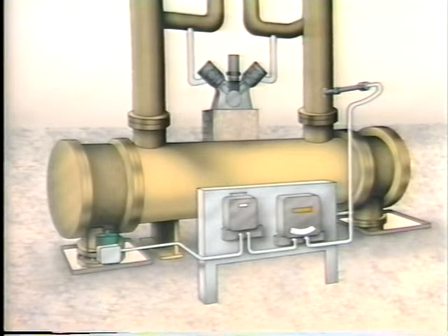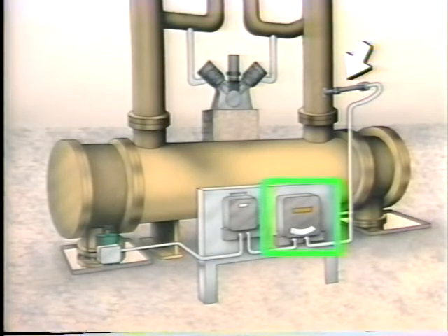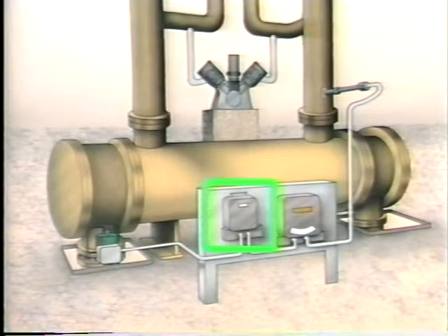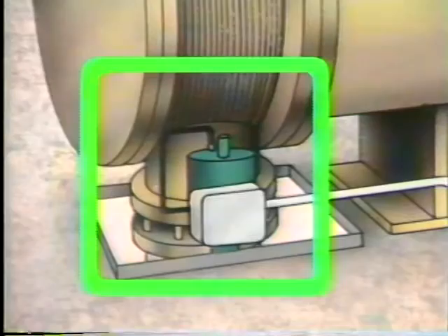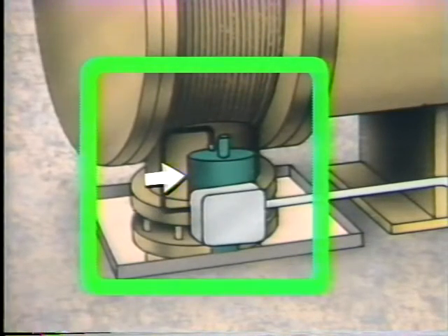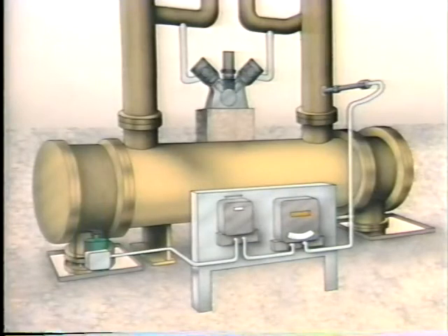The primary element in this system is a temperature sensing bulb and capillary tube that are connected to a sensing mechanism inside the transmitter. The measuring element is another mechanism inside the transmitter. The controlling element is this controller. And the final control element is a positioner and actuator that operates a valve in this pipe. In this system, the elements work together to maintain cooling water temperature at a desired value. Now, assume that the cooling water temperature is at set point. Let's see how the control system maintains cooling water temperature.